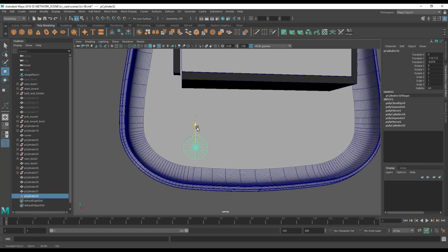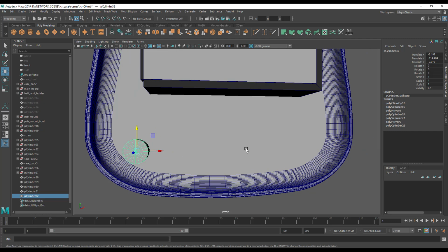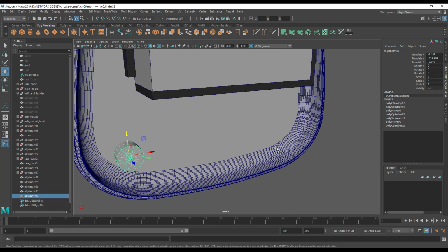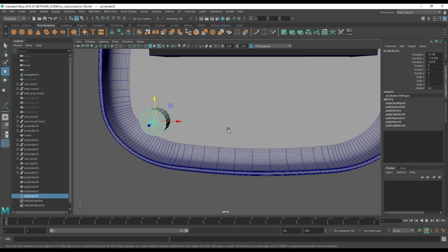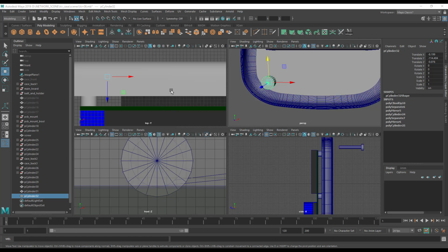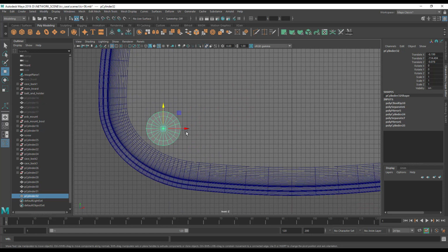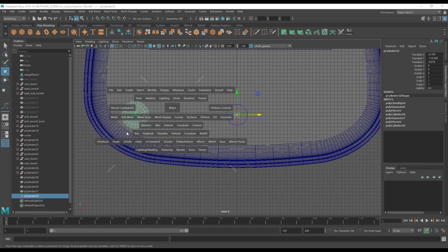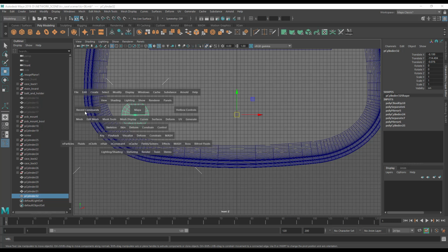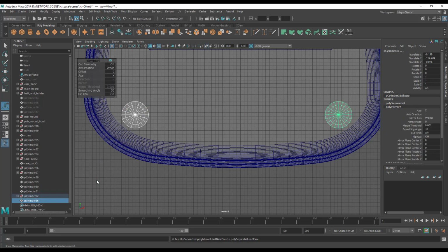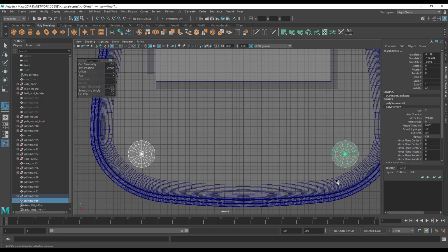So let's use wireframe unshaded, makes me happier. There we go. And I'm going to use the same trick of mirroring this across. Now let me just go here. So let's adjust pivot point. Wrong view, of course. Hit F to zoom in on this, and insert to move the pivot point, and X to lock it to the grid, and whack it out here. And then let's just hit insert again, because we've done this once before, the mirror command should have the same options on it.